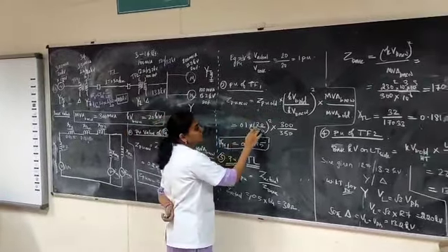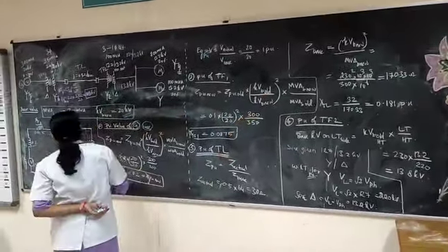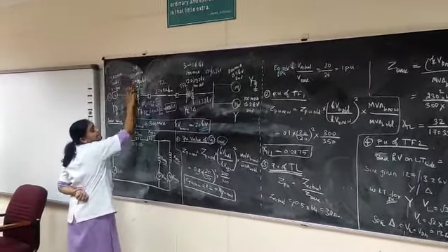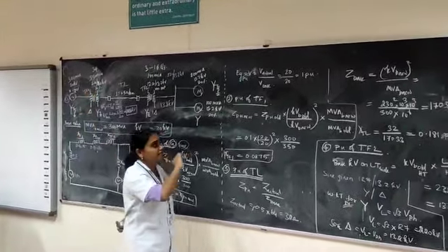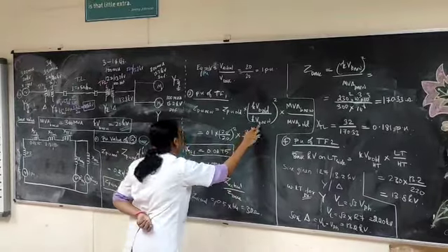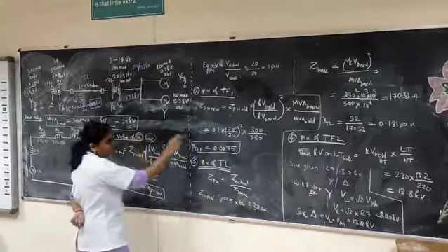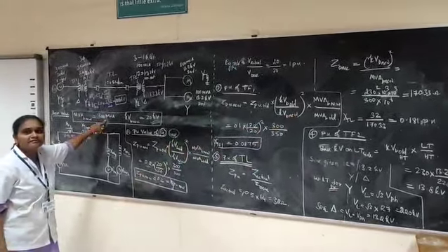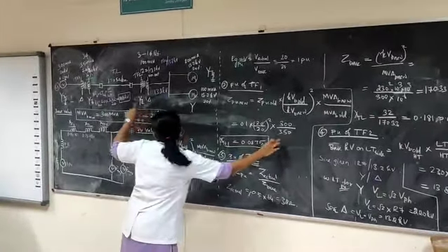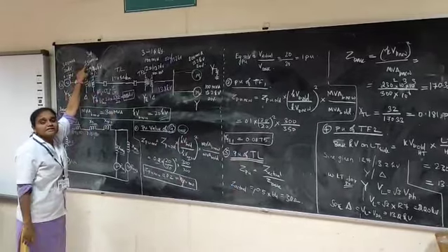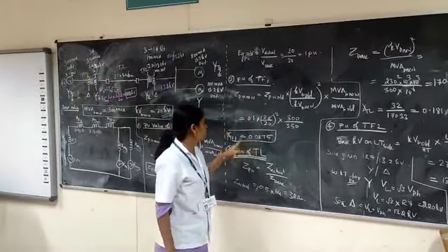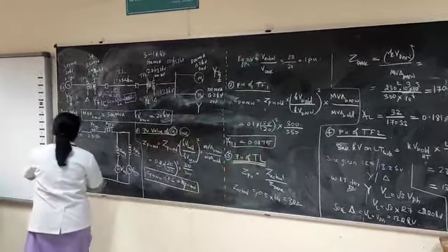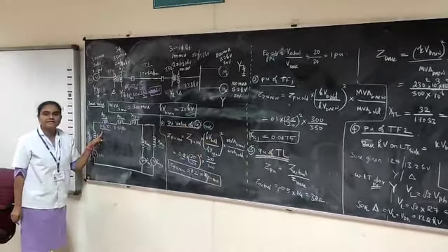So it is 0.1 into kVb old. kVb old means we have to consider the transformer voltage value, which is 20 kV on the primary side. So I have taken 20. Then kVb new, the same base value given here, 20 by 20, into MVAb new, which is 300 MVA, given as base, and the old value is 350 MVA, which is given in the transformer. So I have substituted, and the transformer reactance value is 0.0875, which we have to represent in the reactance diagram.